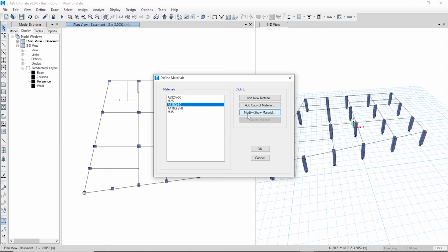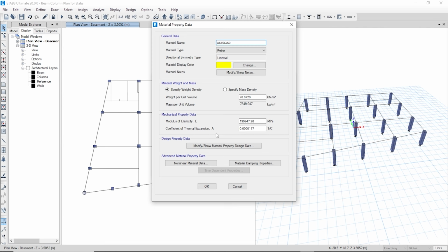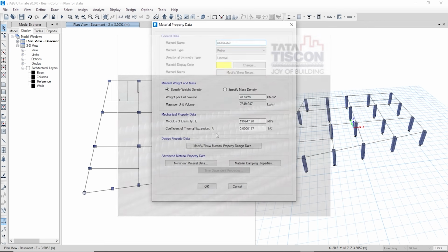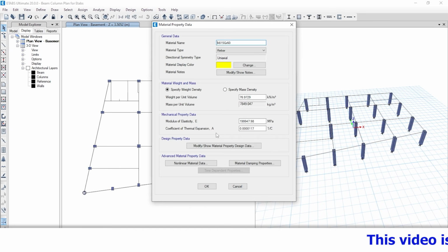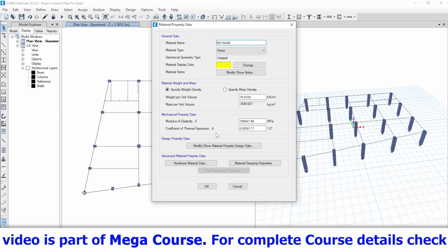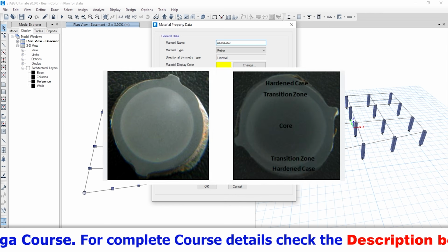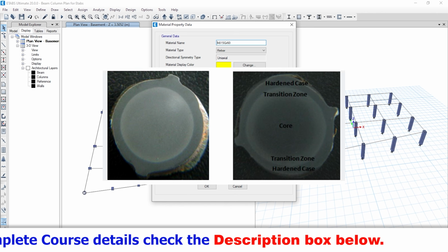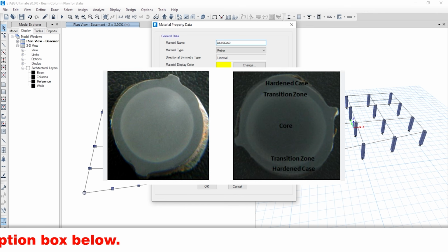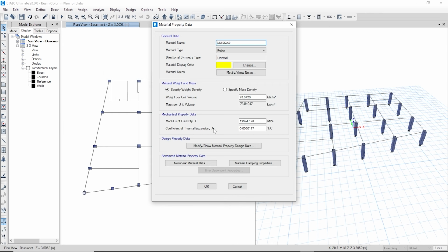Nowadays, we as professional engineers are providing a minimum of TMT 500 bar for any kind of construction activity, no matter how small the project is. From now on, you should not use 415 or HYSD 500 bars for your project. Always go with thermomechanically treated bars called TMT. Compared to HYSD bars, they provide good ductility with strength as well. We have discussed a lot about these bars in our mega advanced courses.